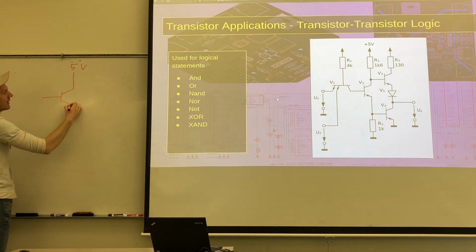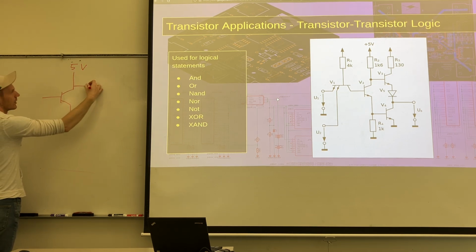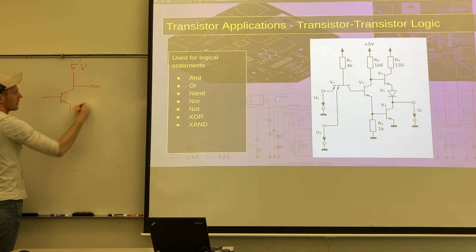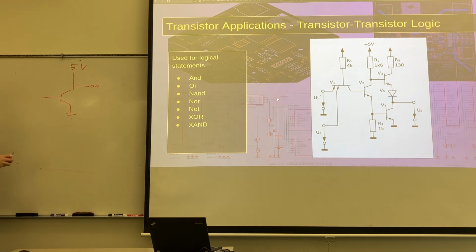5 volts and out and ground. Imagine some resistor here maybe. And this is your input signal. So a NOT gate in this case, if you put in a logic 1, which in this case is 5 volts, so you apply 5 volts to this, this turns on and conducts, this shorts to ground, all the voltage is dropped here, this is shorted to ground, this says 0. So you put in 5, digital 1, you've received 0, digital 0.